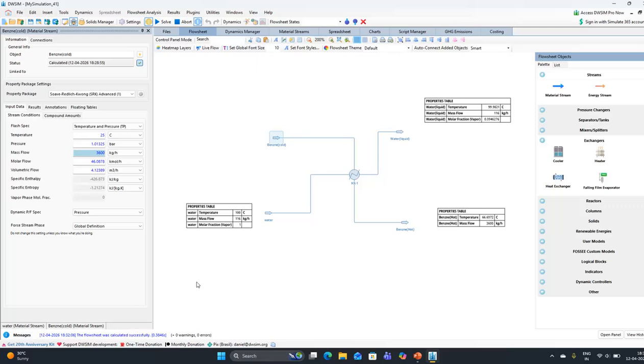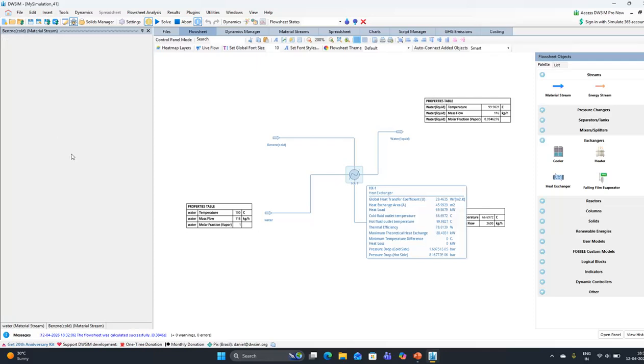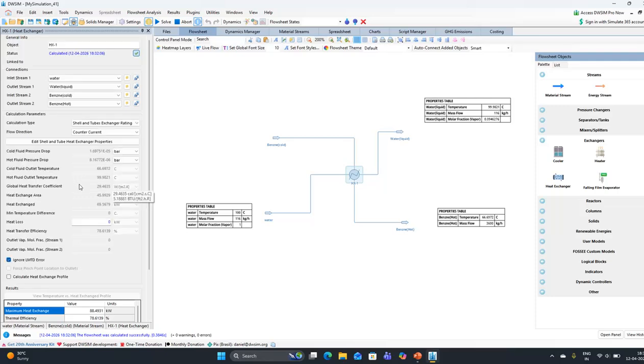Now you might encounter design problems where this temperature you also need to negotiate. In that scenario, here I am doing shell and tube heat exchanger rating; you go to the fouling calculations, and in that you just change it to, let's say, 80.